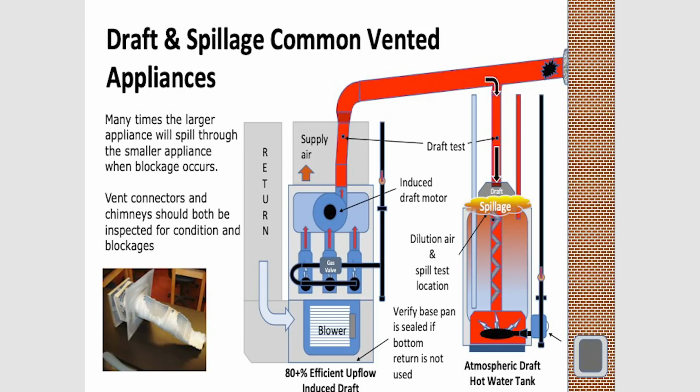When you walk in, a lot of you guys don't realize part of the International Fuel Gas Code and part of the National Fuel Gas Code is actually inspecting the chimney when you go out there and do a service on there. So you're supposed to actually take the chimney apart, take the stack off, and take a look inside there.